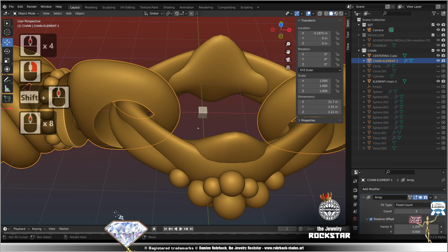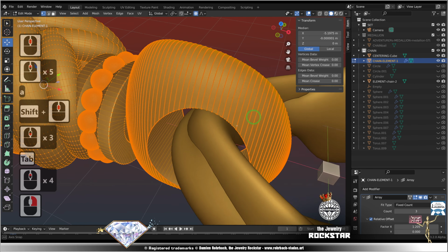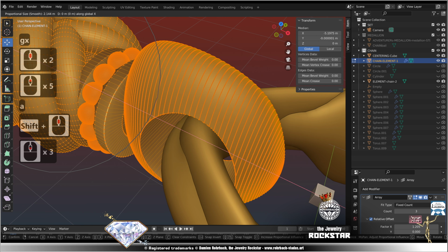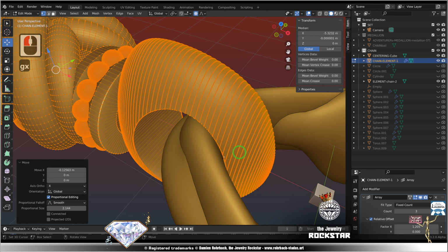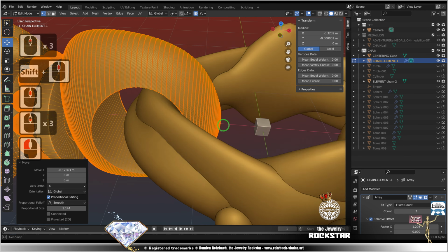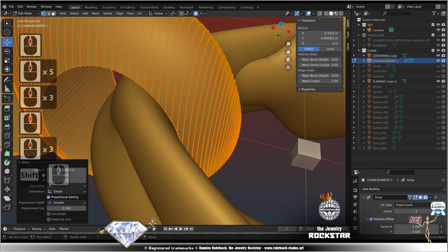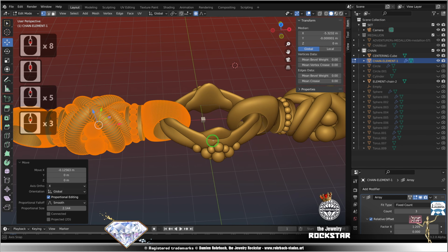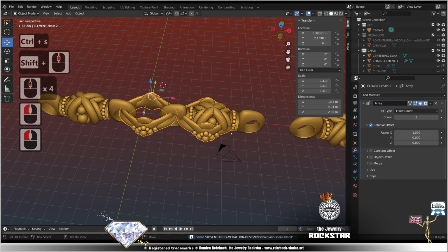So I'm going to come here, edit mode, A, and let's adapt GX. Have a look at which corner or which part or vertex is touching first, and then I give it just a slight distance, because in real life that's what happens.